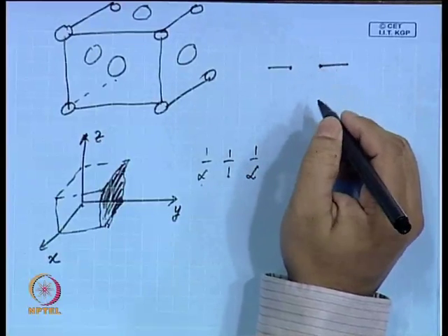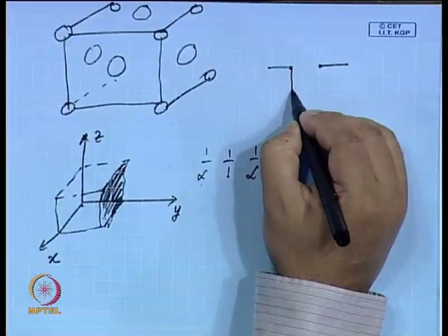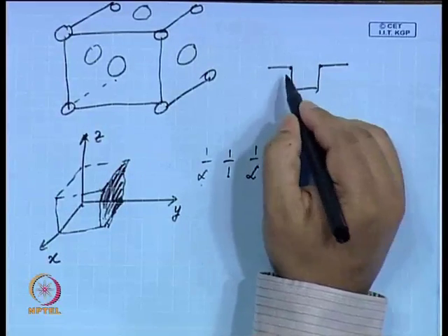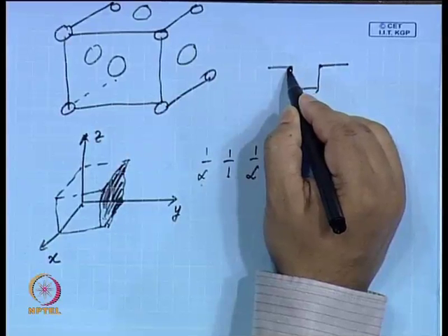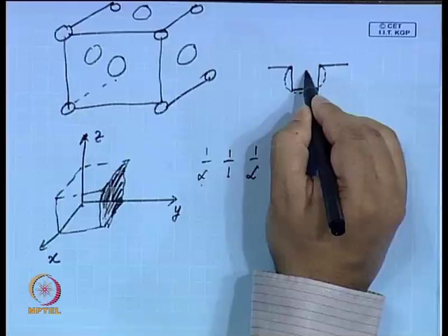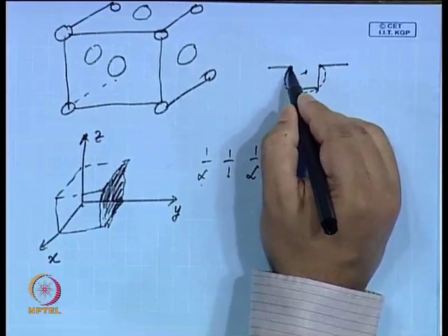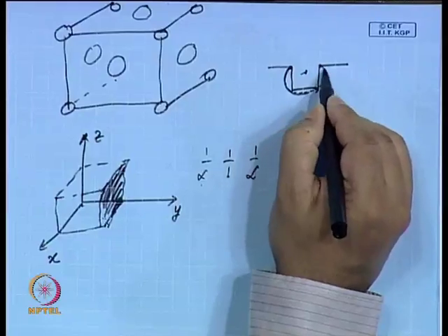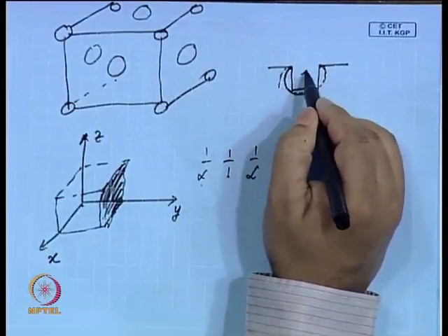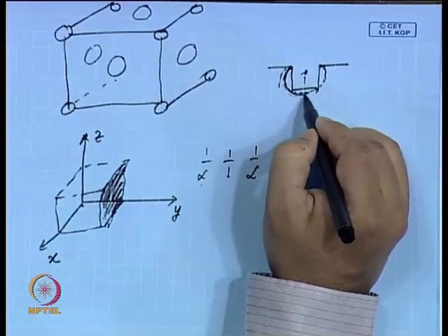been taking place uniformly in all directions, then it will not be this. This does not mean it is uniform in all direction. What it means, uniform should be this. Think of it, this is the point from which the etching is taking place and you should form a circle, uniform in all directions. So, gradually this would be changing because the etching center would change. Okay. So, this is called isotropic etching.